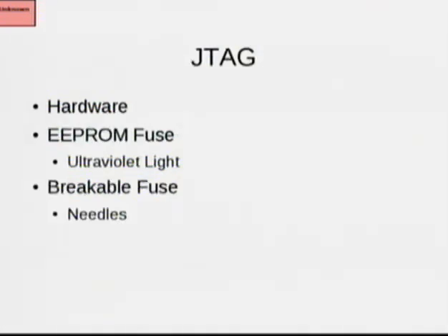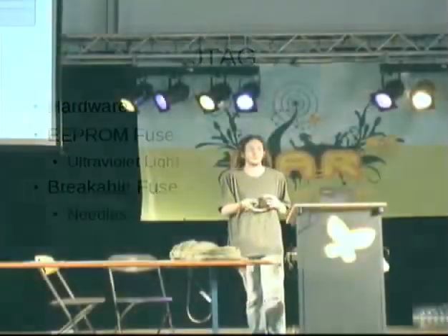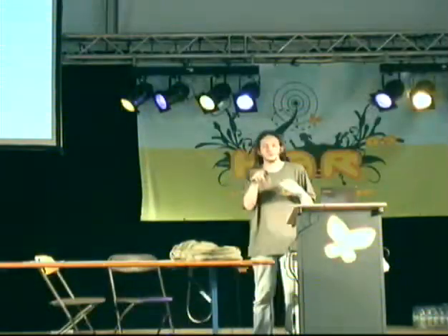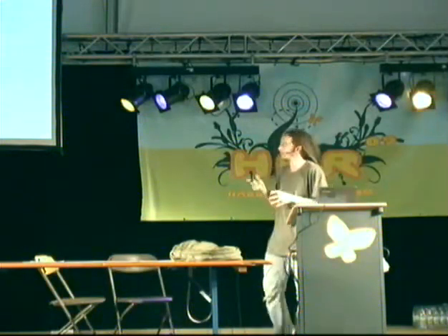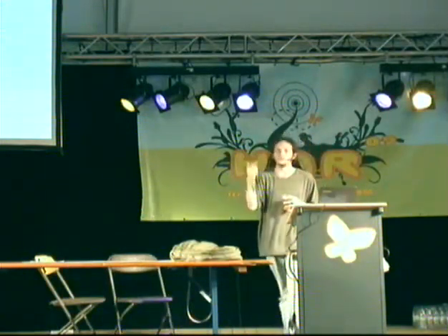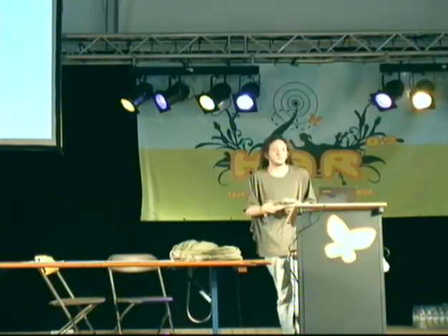JTAG is a hardware protocol. There is no JTAG server application running within the chip. Instead, there's a hardware state machine. And the state machine allows for exchanges of bytes in a similar way to SPI. But it also has a state machine that you can wander through. So you go through different positions. There's one position that says you're shifting bytes into the instruction register, another that says that you're shifting them into the data register.